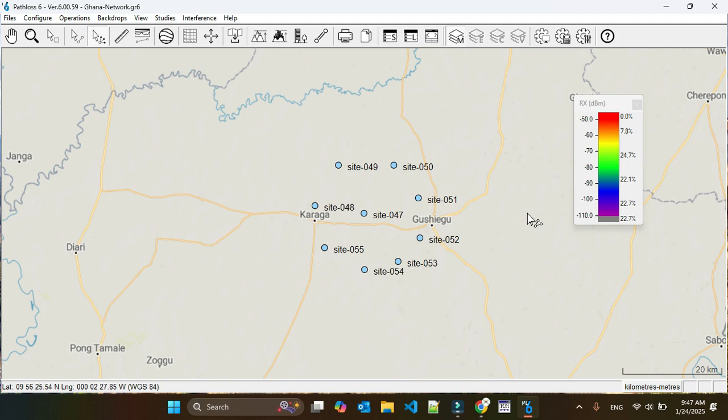Usually, not always, but in a point-to-multipoint link you have some kind of base station in the center, which has some sectors, like 3 sectors or 4 sectors, sectoral antennas, and then you connect multiple sites to it. So it generally gives you some kind of gain for the usage of the spectrum. But this is, you can say, the planning part of it. But how to create those links on path loss?